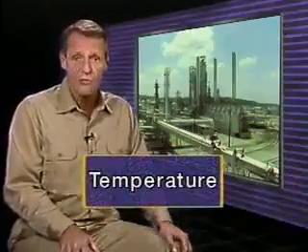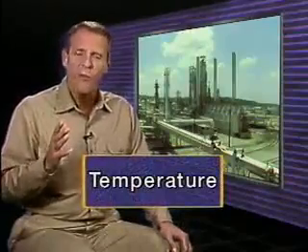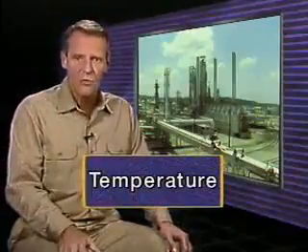Scale and sludge can form inside pipes and equipment and reduce their capacity. Scale and sludge can also reduce the efficiency of heat transfer in equipment. The amounts and types of dissolved solids that water contains depend on several factors. One of these is the temperature of the water. Typically, the higher the temperature of water, the more dissolved solids it can hold.